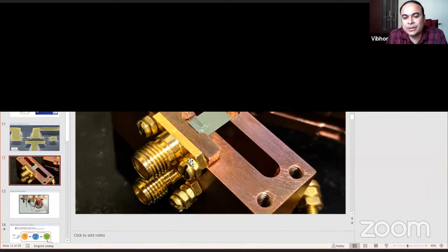The experiment demands that we apply a magnetic field, and then the only choice of material for the 3D cavity is copper. So there are of course resistive losses in copper, and typically you get about a 2 megahertz linewidth for a copper cavity at millikelvin, and that's what we also observe.